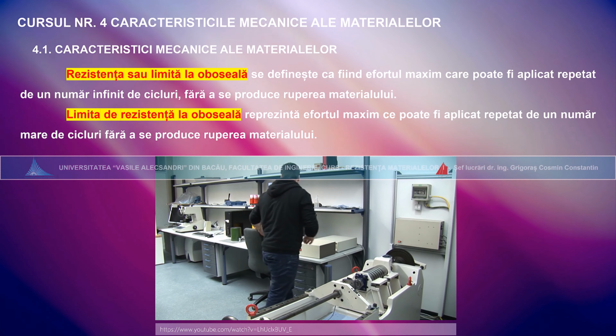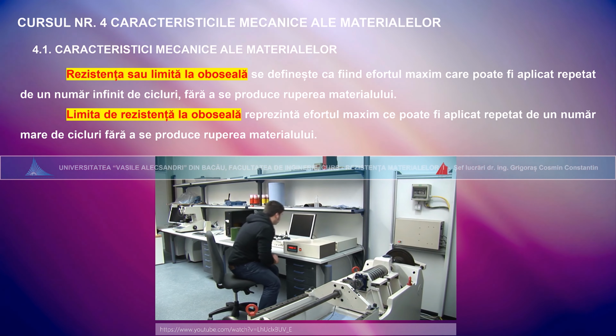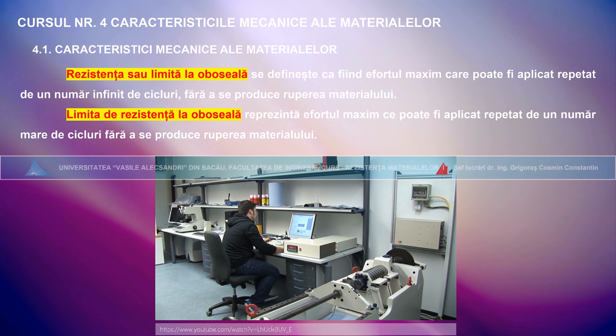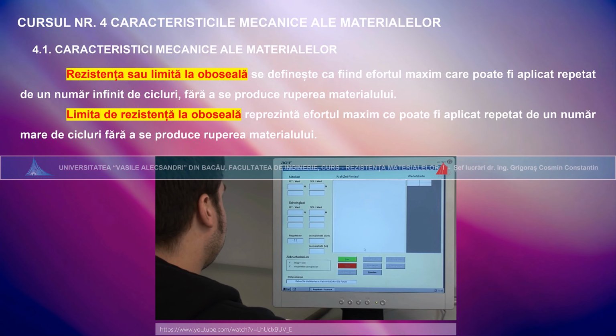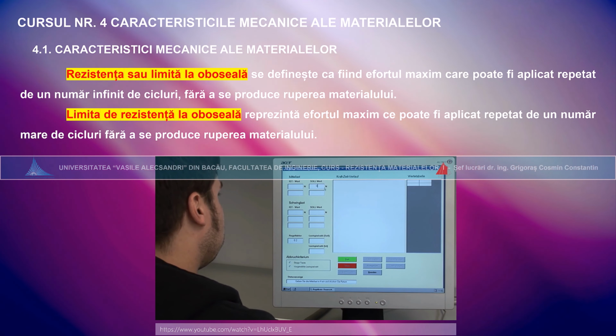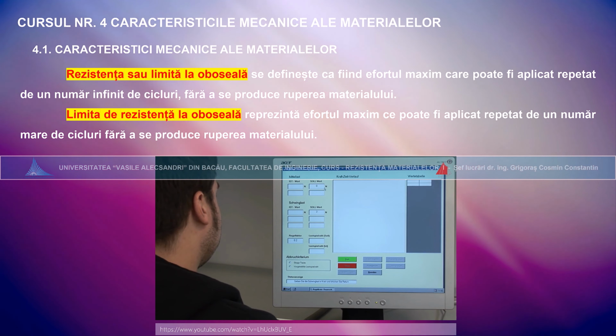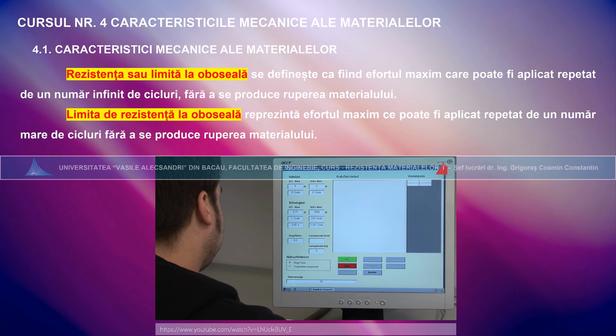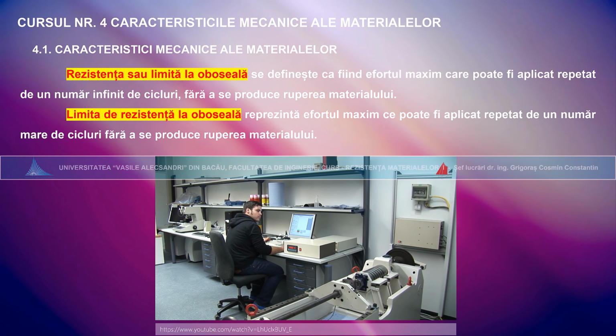The material tester then selects the appropriate test parameters on the control computer. He intends to load the first specimen alternately with a tensile force of 7 kN and a compressive force of 7 kN. The mean force is 0. A click on the start button and the testing machine begins to stress the specimen periodically.